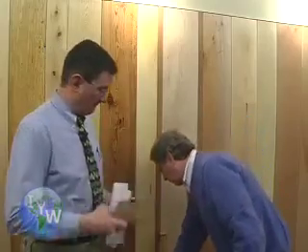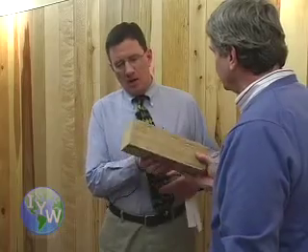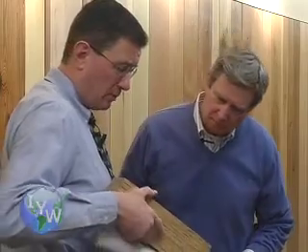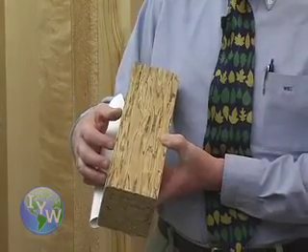Okay, now I want to skip ahead to this because this is fascinating. I hope people at home can see the texture of this, but this is what you would call an engineered product? This is an engineered composite wood product, and it's manufactured by taking veneer, which has been peeled, and the veneer you normally think would be put into plywood. But in this case, the veneers are sliced and chopped into strips, maybe something along the lines of 8 to maybe 20 inches long, and about a half or 5/8 of an inch wide.